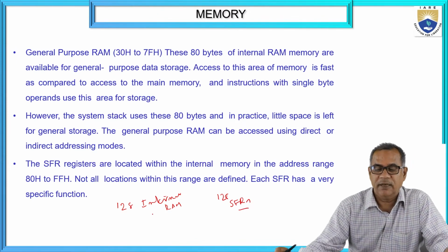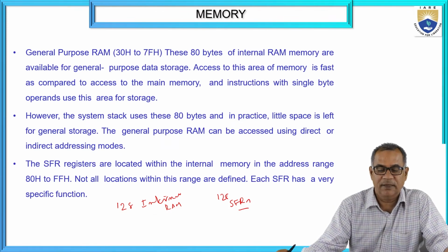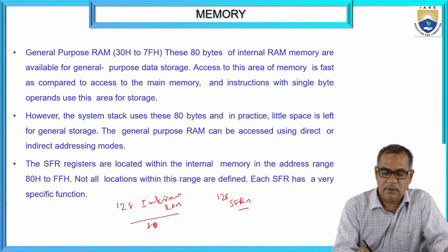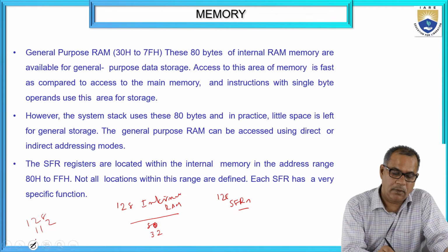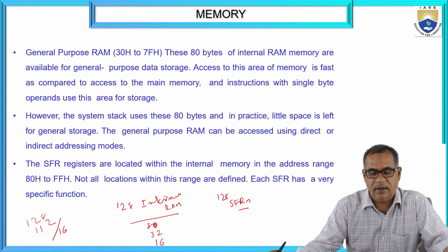So in this internal RAM, you have 80 bytes allocated for general purpose RAM, and 32 bytes are allocated for the register banks, and there is a bit addressable RAM which is of 16 bytes.